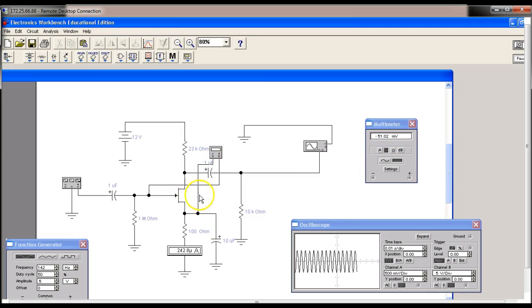Well, how did that minus get there? Well, when this current flows through the resistor, it drops a voltage, which means, and here's your positive up here, and remember when you measure, you set up the polarities on your resistors back in DC, the side of the resistor that's closest to the positive, or vice versa, gets the positive sign. So this would be positive, negative in respect to the other side, and then this right here would be positive in respect to this. But this is common.